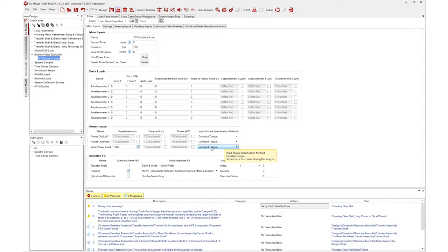However, we do have the ability to change this to use any imported electric machine excitation data. So this is the data set that was imported. And then basically what I do here is I define an input speed at that particular electric motor, and then it will calculate the rest for me. Once we've done this, we go forward to our NVH mode.